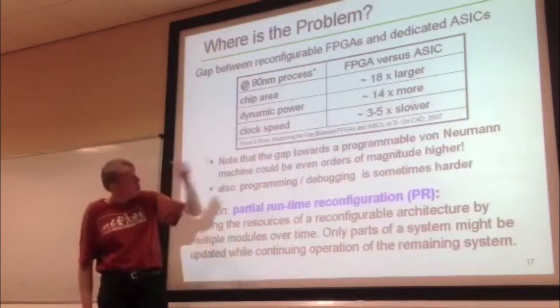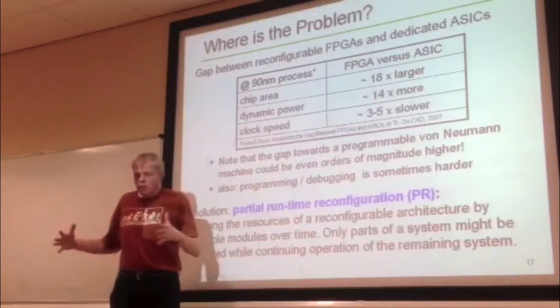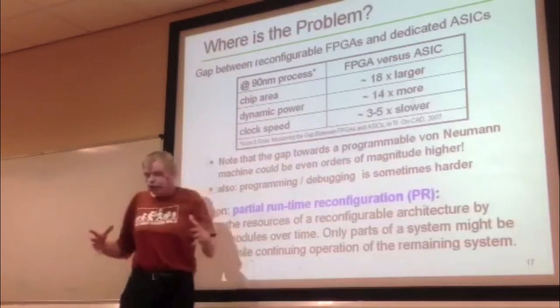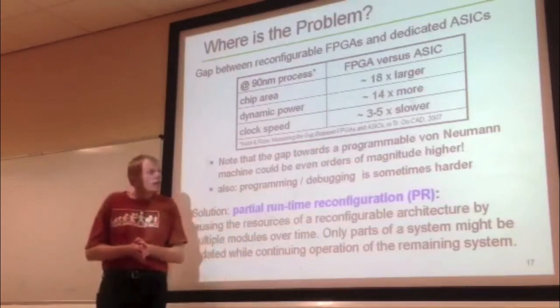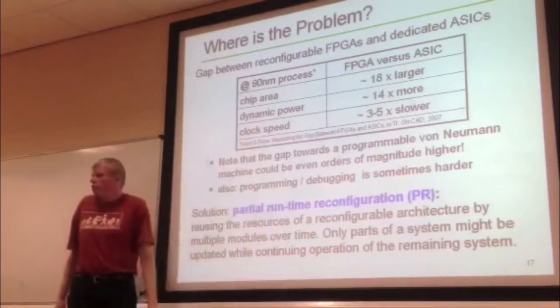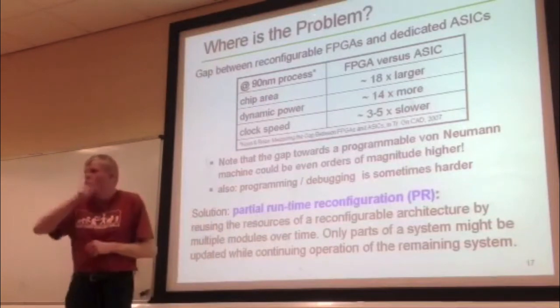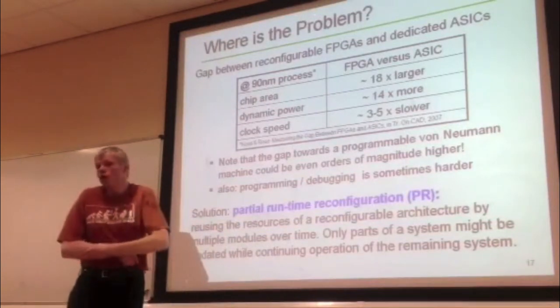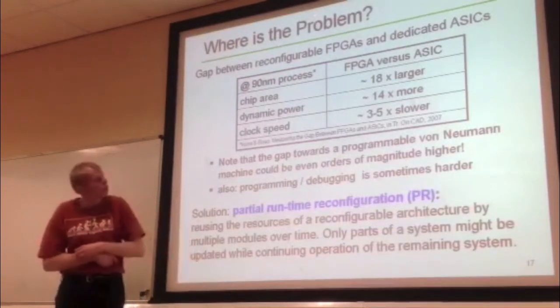In terms of an FPGA as compared to an ASIC, where an ASIC is a chip that's done for one specific task, here you have something that is reprogrammable for many different things. And this reprogrammability, for example, all these wired interconnects I showed you, produces a lot of overhead. And this is really significant.